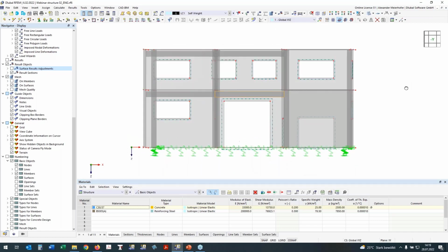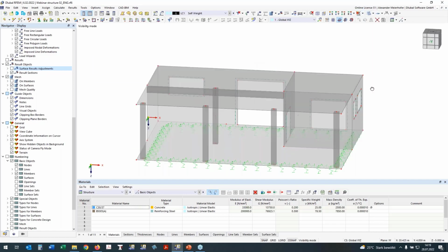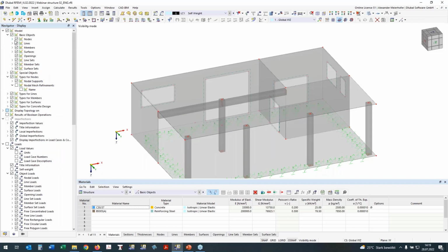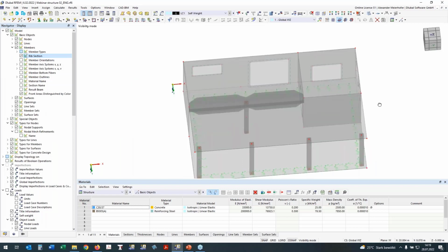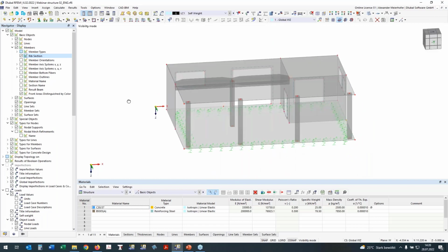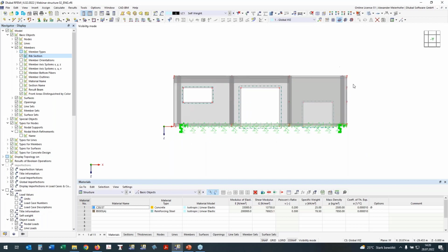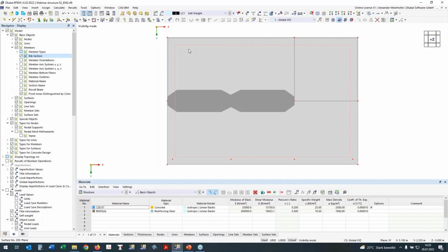And now I do it again what I did before. And a very nice feature from RFEM 6 is now that we can show the rib section also in the graphic, and we see that the integration width is also shown here in our main graphic of RFEM. Okay, now I will select again my slab here, and will continue with the definition of the design properties.